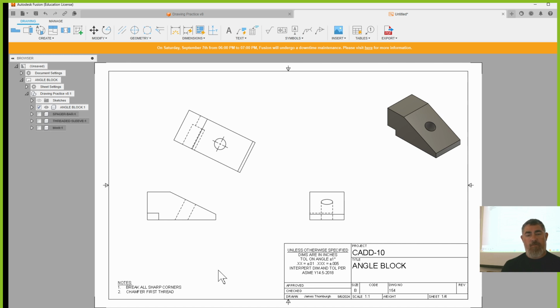When you're doing a center mark, occasionally on drawings, I've noticed that the center lines will extend to different views. Can you do that here? No, don't do that. People that do that are doing it wrong. That is against standard.